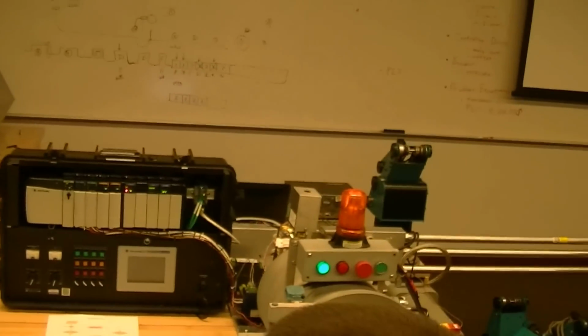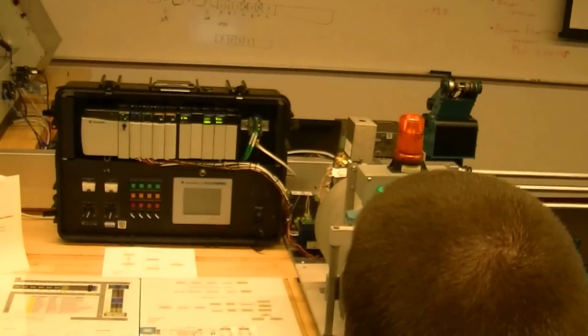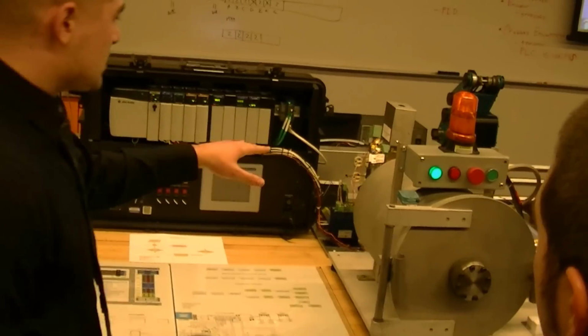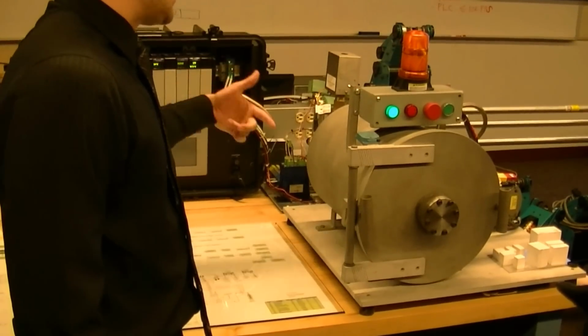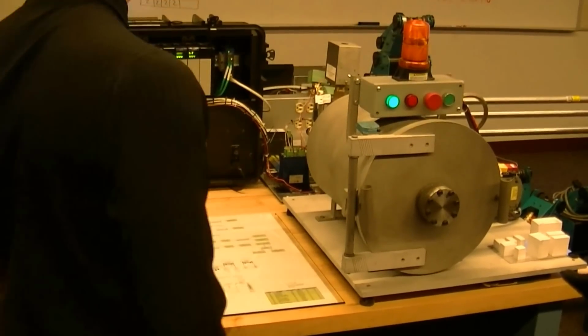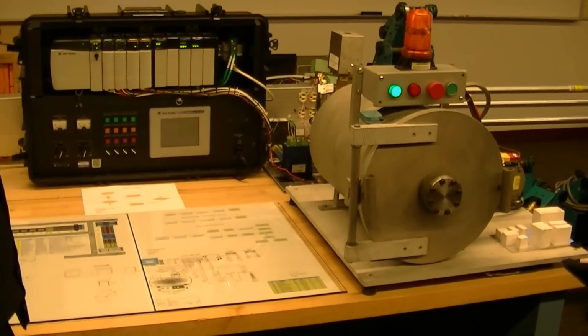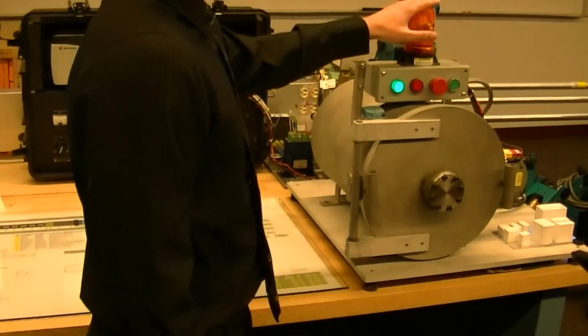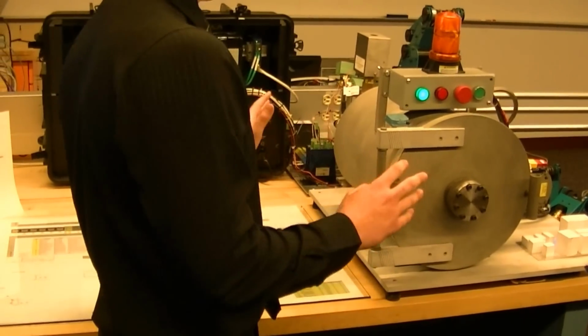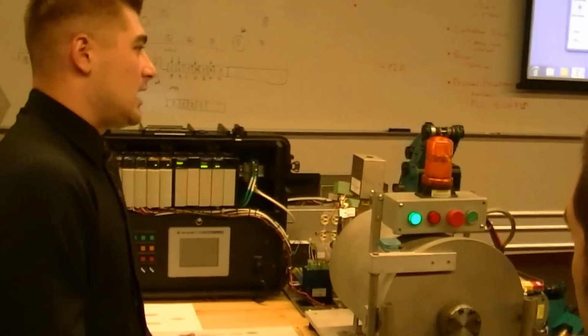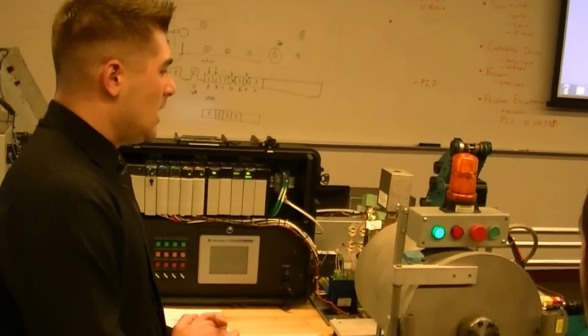And there's our process segment ending, and that's your final purge sequence. So we open up a purge exhaust valve on the back, and now we're blasting 100% argon into there and cycling through the cooler. This is going to take place for 3 minutes based on our recipe. This light indicates that it's purging hot air, so someone in the back can understand that I shouldn't be back there because I might get steam or hot air in contact with myself.